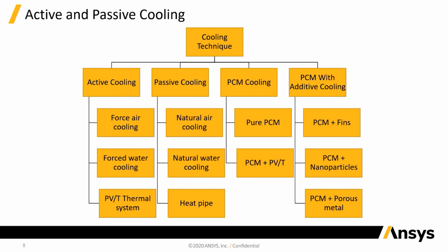When it comes to passive cooling, we have natural convection cooling where there is no fan. It's just based on the temperature gradients in the air surrounding it, which drive the circulation of the fluid, and that drives the heat transfer. Immersion cooling is now a coming technology for servers, where all the electronics is embedded in a non-conductive liquid, and that liquid drives natural convection currents based on the temperatures and keeps the system cool. So that's a kind of natural liquid cooling.